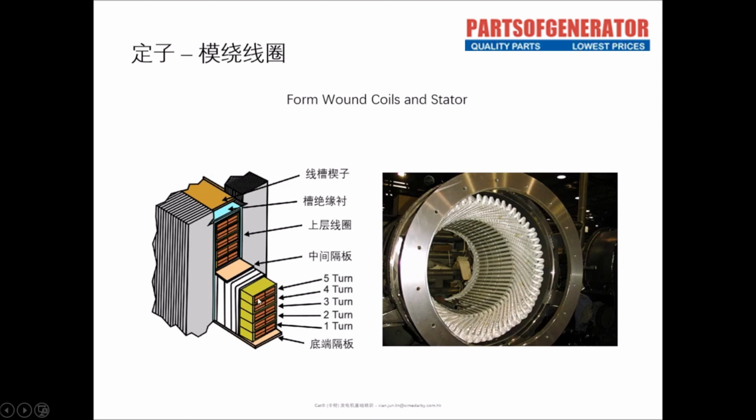Then we look at the cut section of this coil. From the cut section, we find that the wires inside are not as we saw before. The enameled wire in the scattered winding coil has a circular cross-section. The cross-section of the mold wound coil is a square or a rectangle. Of course, it is actually a rectangle with rounded corners.